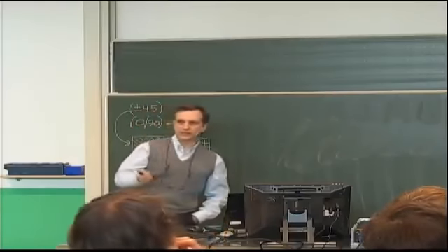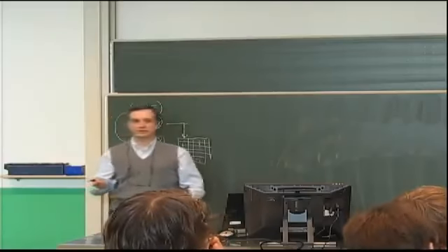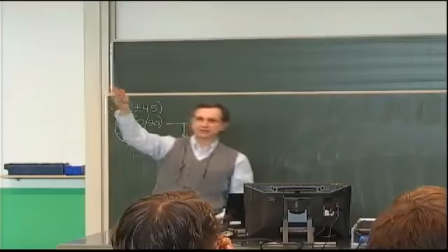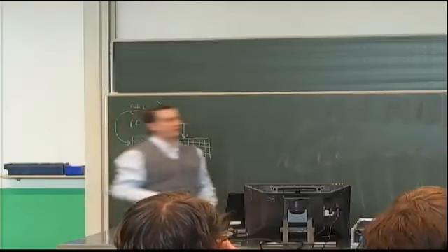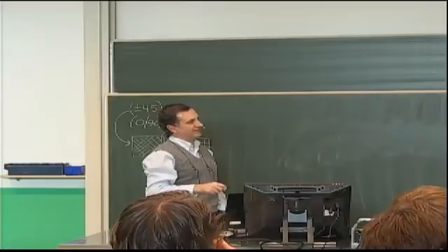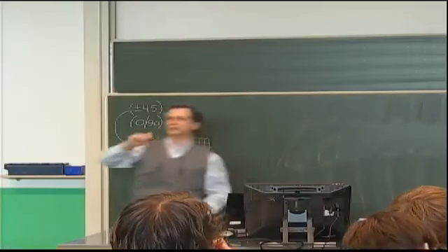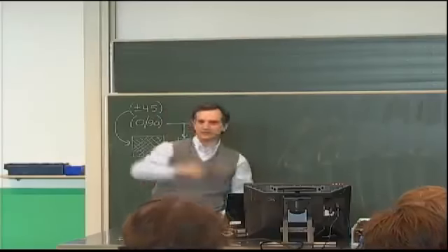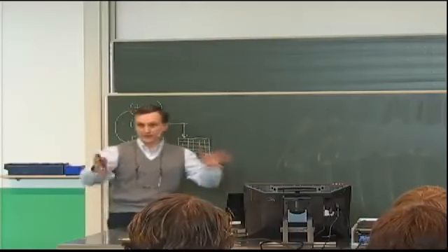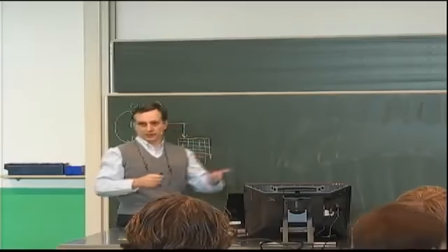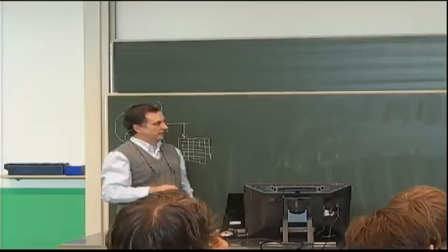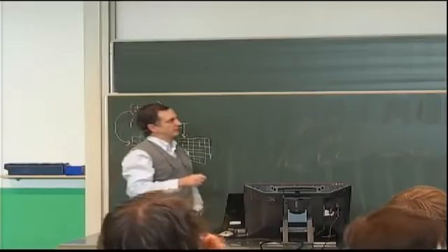Now, why are we not exactly at x equals 0? Yeah, exactly. There's no point. We know there it's 0. Plus the exact value there is where the Gaussian integration points were in the finite element model, where we know the solution from the finite elements is exact within the finite element concept. So it would be the most accurate location closest to 0 in this case that we can then use. And you can see that the two solutions are on top of each other.